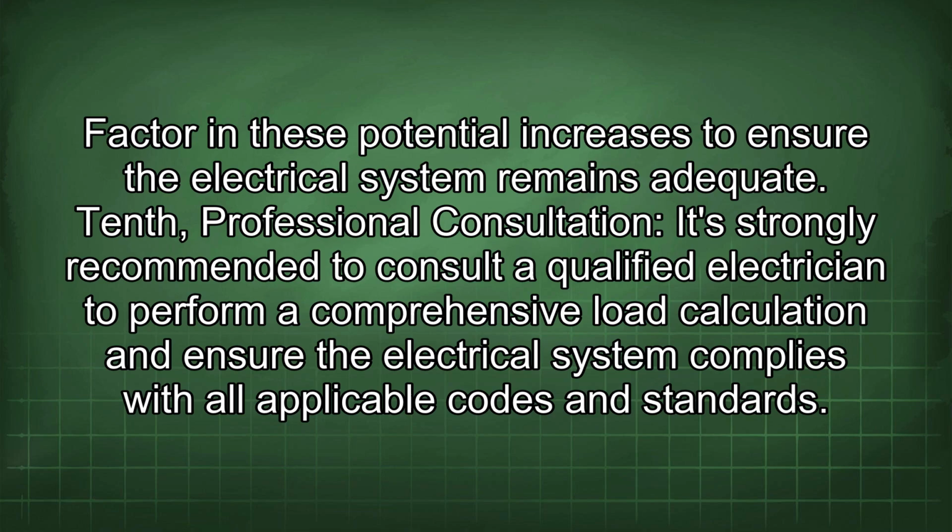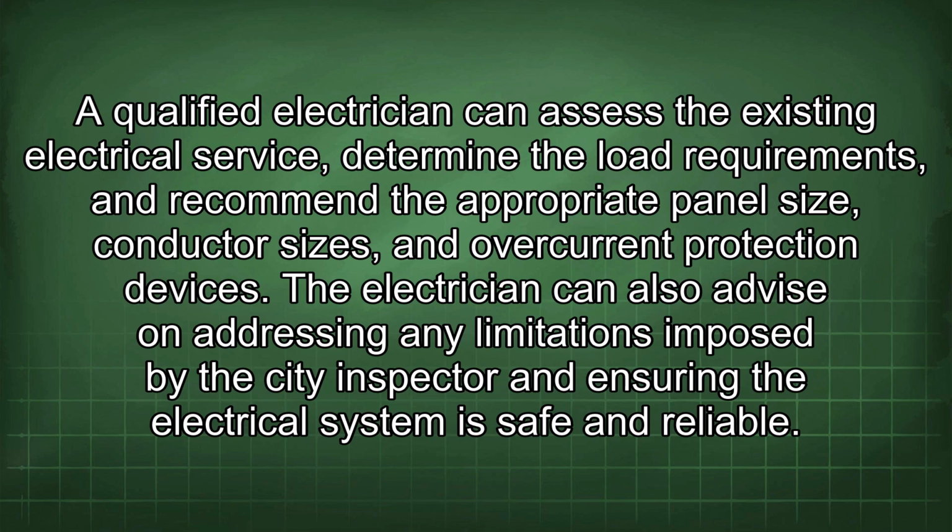Tenth, professional consultation. It's strongly recommended to consult a qualified electrician to perform a comprehensive load calculation and ensure the electrical system complies with all applicable codes and standards. A qualified electrician can assess the existing electrical service, determine the load requirements, and recommend the appropriate panel size, conductor sizes, and overcurrent protection devices.